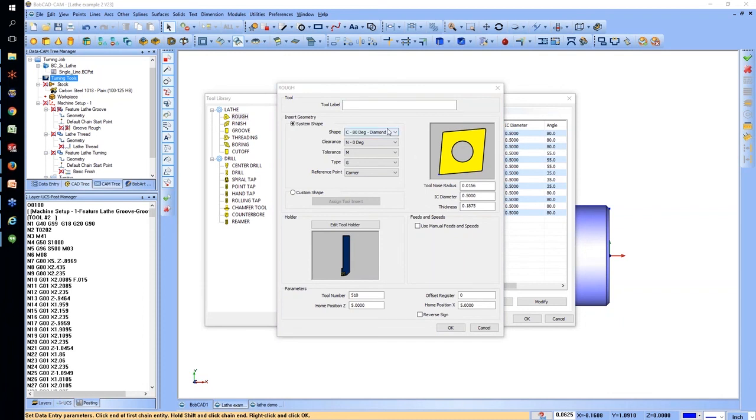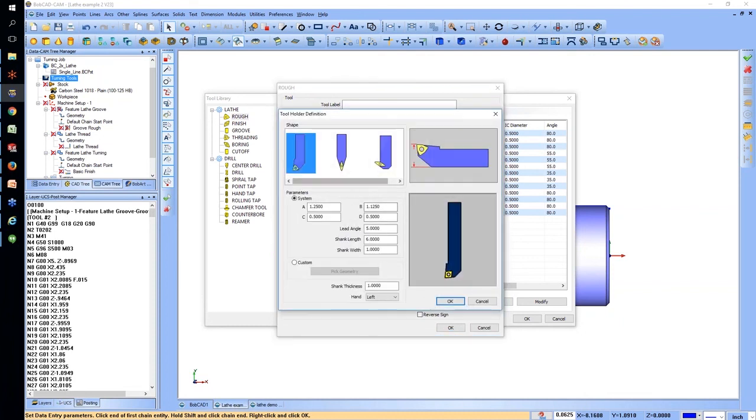Because right here on the actual piece you have obviously your shape, okay, diamond, triangle, square, rounded, okay. You guys also have your clearance options here. You really don't mess with too much of the orientation here. It's more in the feature where you can say it's horizontal or vertical based on the tool options, and that's where you can also process the insert when you have the tool holder. How's the insert versus the actual holder? Okay, the shank length, the shank width, you guys can handle for the insert too.